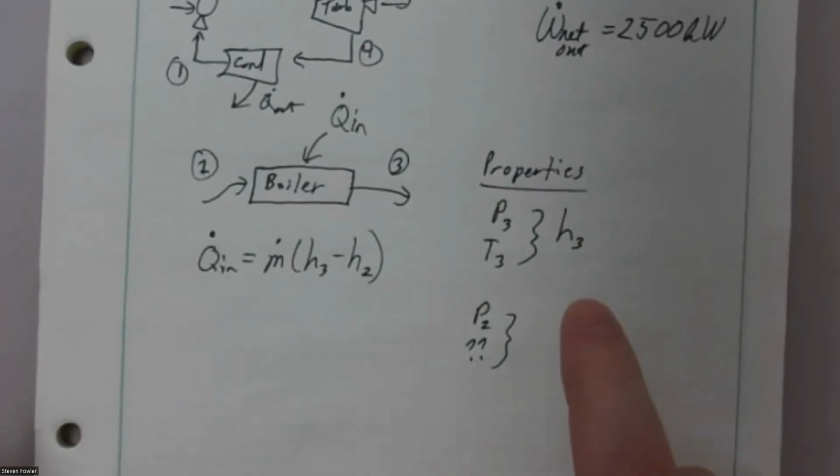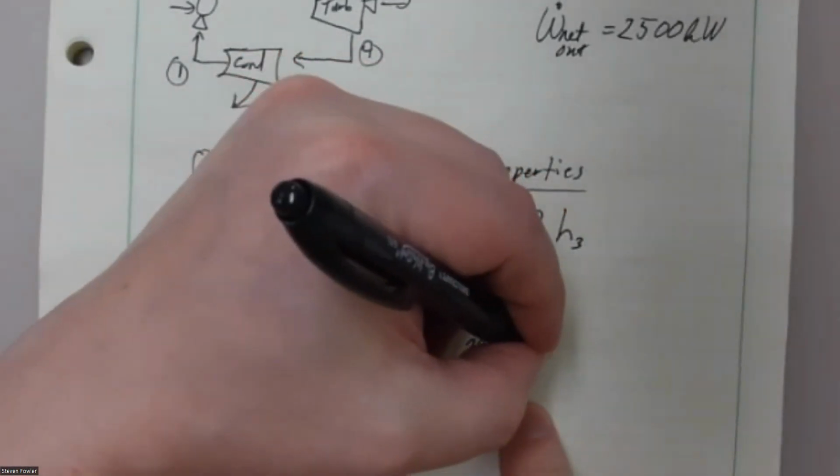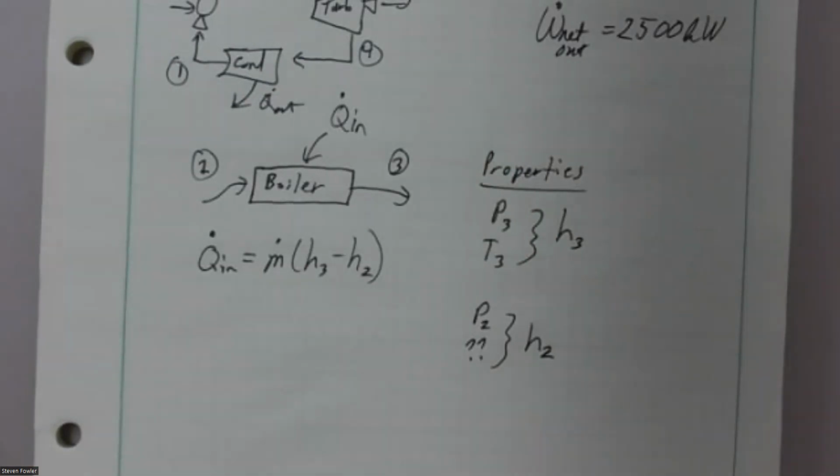All right. Now, getting to H2, and by the way, the secret to a Rankine cycle is can I get H values around the entire cycle? With an Otto or diesel cycle, the secret is, because it's an ideal gas, can I get temperatures all the way around the cycle? If I can get the temperatures, I can find all the other properties. In a Rankine cycle, the goal is really going to be, can I get to the enthalpy at all points in the cycle?